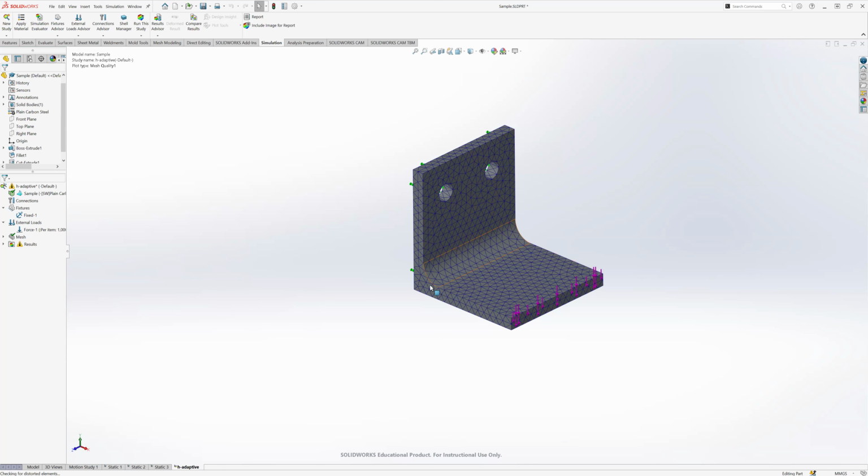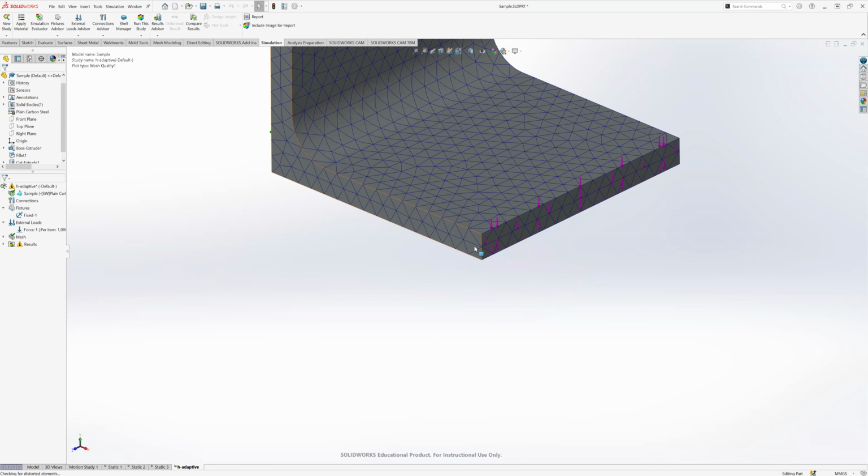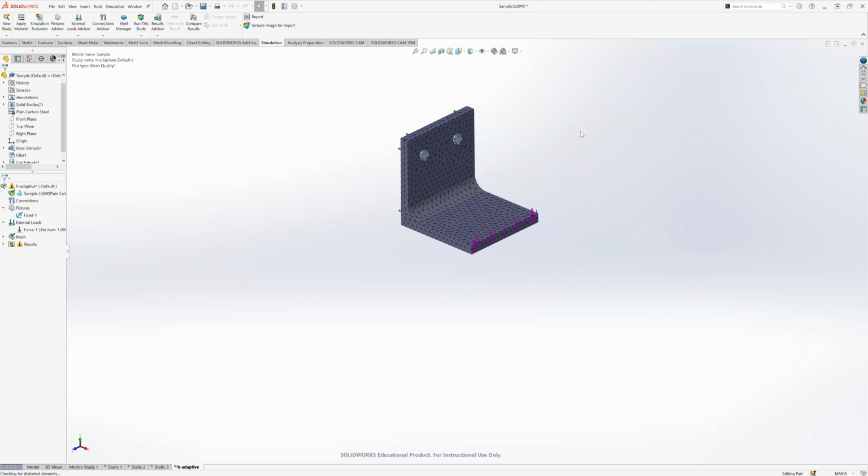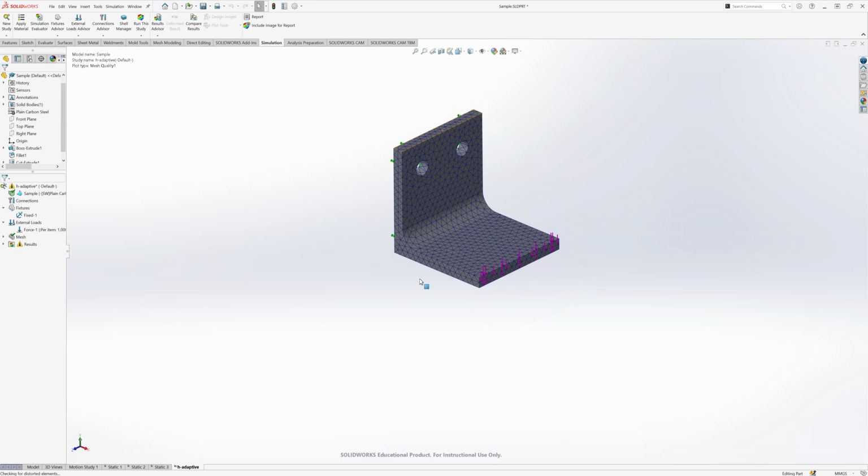Again, if you have that mesh coarsening, it can make areas that don't have a lot of stress a bit coarser. But again, there are only 2 elements across here. I don't really want it to start doing maybe 1 element across, because then I might start losing accuracy here. So I'll stick with this and have it make it finer from here.